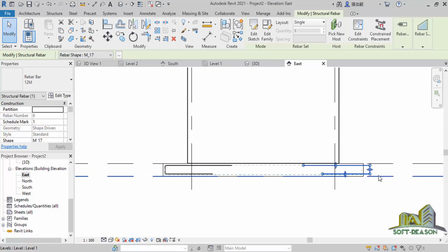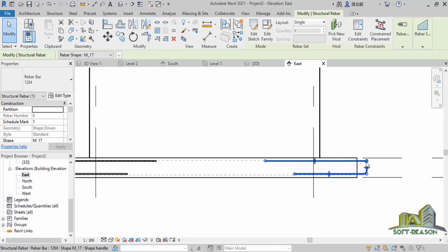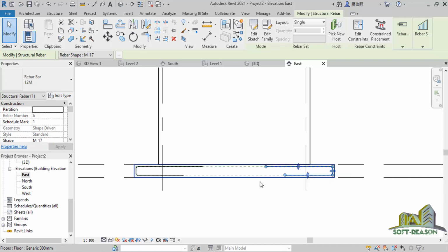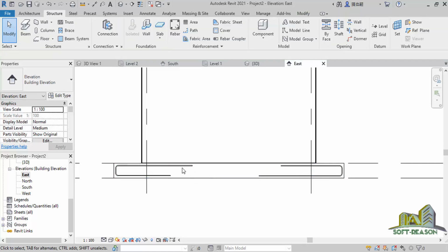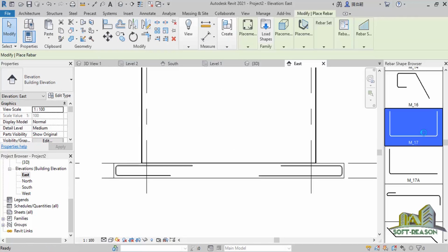So you can see this has actually shot out, so you can't use your arrow key to shift it. Okay, just like this. So you'll be having something of this kind. So in this case, this side will be longer. Okay, and this side will be shorter, just like this. Alright, so the next one is the horizontal bar. Okay, so click on the Rebar in the Rebar browser.